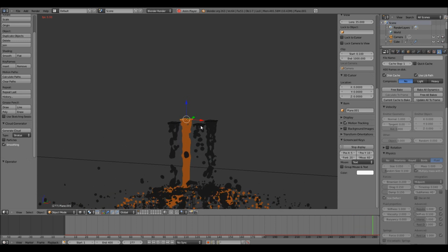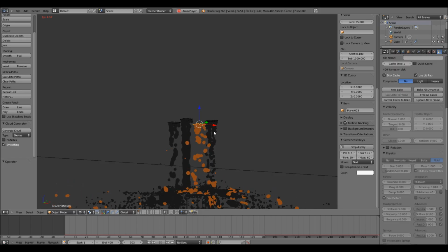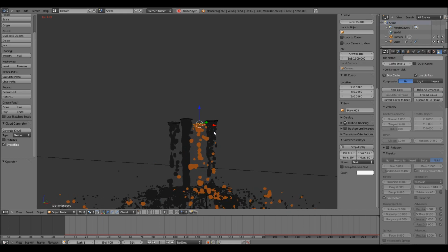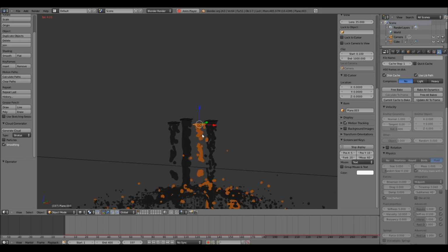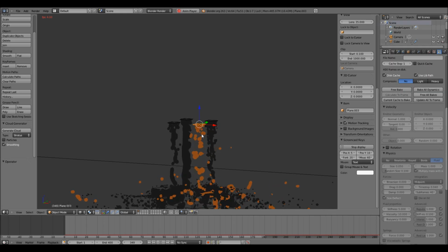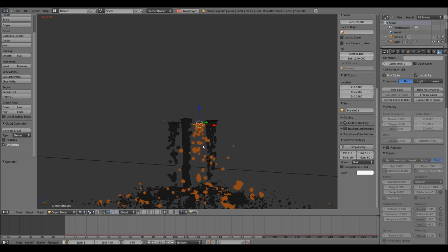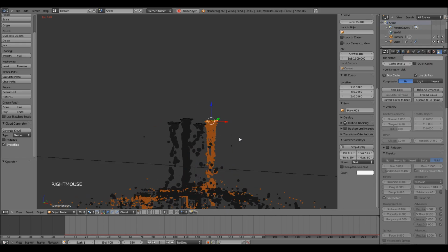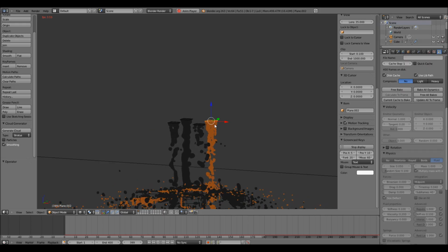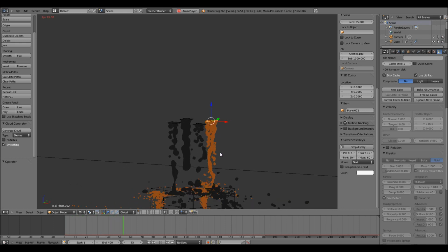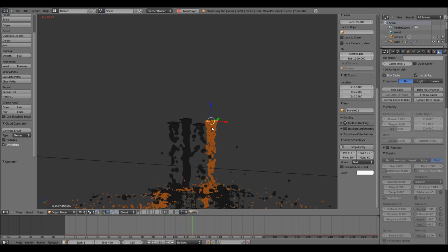Same goes for example, the second particle system, which has the high stiffness and viscosity. I think the settings I used here are not so good. That's why this is not really behaving as I expected. But still, the difference between the first particle system, which is the default one, and this one is clearly visible. Same goes for the third one, where the stiffness and viscosity is set to very low values. So this fluid looks more light, or less dense than the first one.